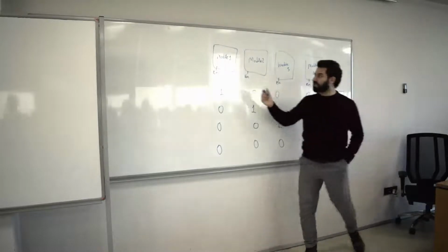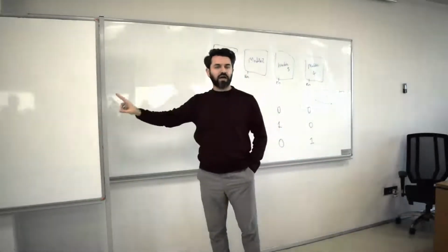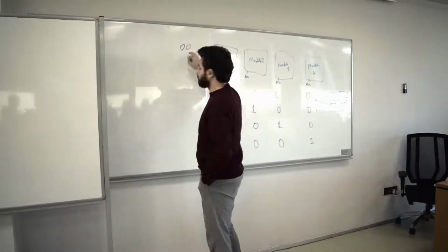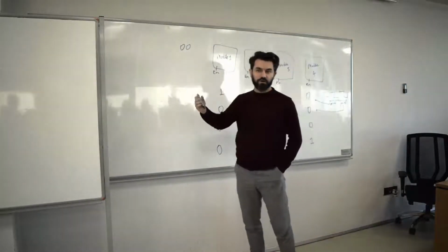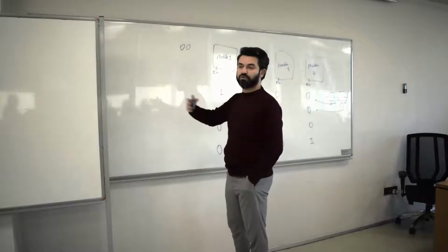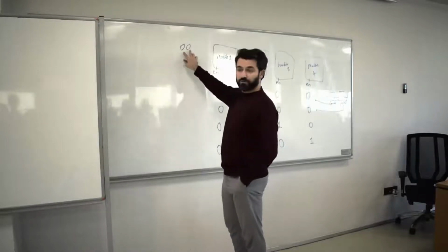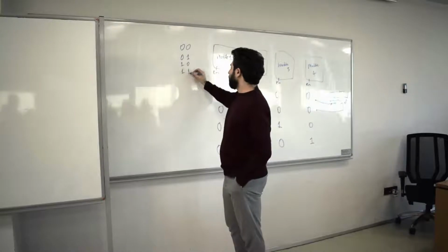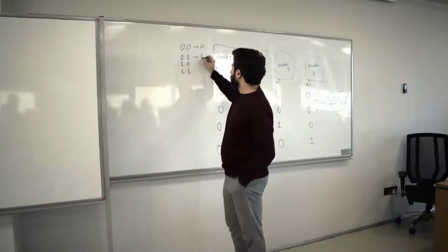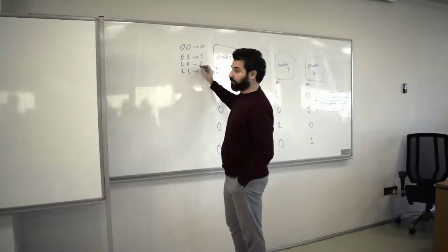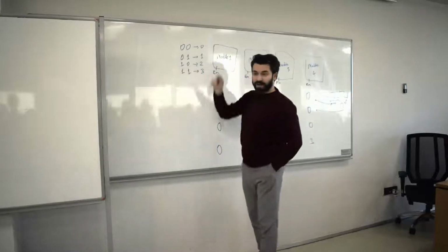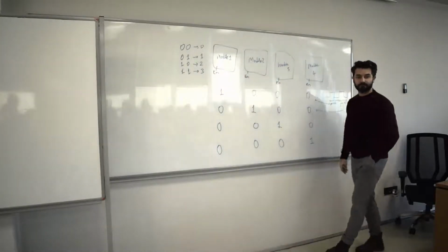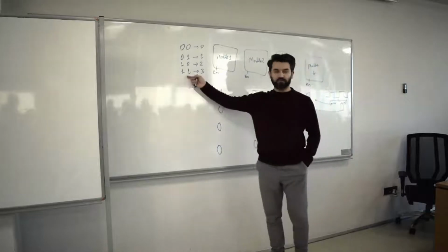It's not like this, right? The conventional counter starts from 0, 0, 2 bits to count 4, I mean to count modulo 4. It starts from 0, 0, goes 0, 1, and then 1, 0, and 1, 1. That corresponds to 0, 1, 2, 3 in decimal format, right? And then it goes back to 0 again. So this is your conventional counter.